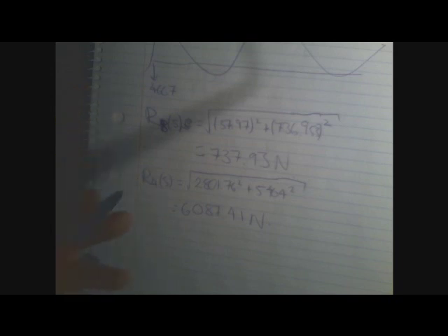To find them at a dynamic load, we substitute WS for WR. Then we recalculate our reaction forces in the XZ plane, not the YZ. Then we just do this again and it'll give our dynamic forces. But from here we can then calculate our desired bearings, or whether the bearings we've chosen fit, work, won't break.